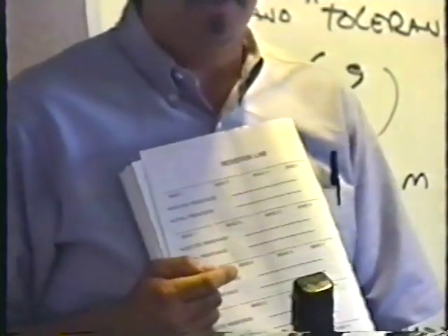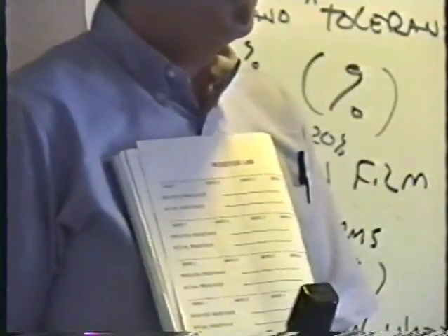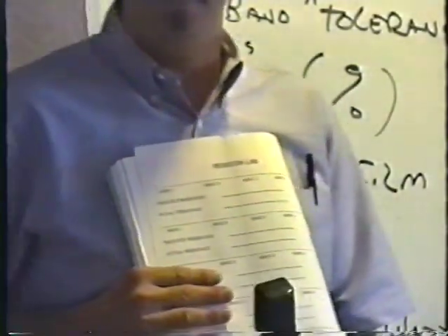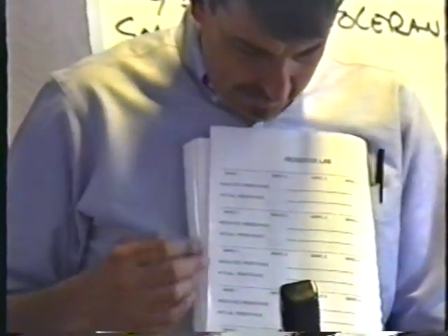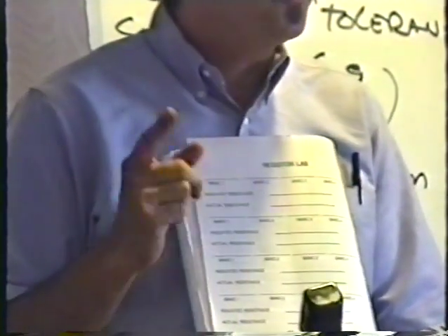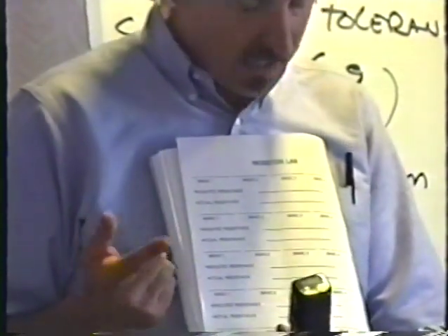I want you to look at your resistor, try to figure out what color it is. If you cannot figure out what color it is, as I often have trouble doing, sometimes you may have to simply measure the resistor, get an idea of what the value should be, and that'll tell you what the colors probably are. If not, ask Shirley or Susan, right? Yeah. What the colors are, because for sure they'll be able to tell us where we probably can't figure it out. Indicated resistance. What is the color code telling you the value should be? What is the color code saying? How many ohms should it be? Then I want you to measure it with your meter and see what the value actually is.